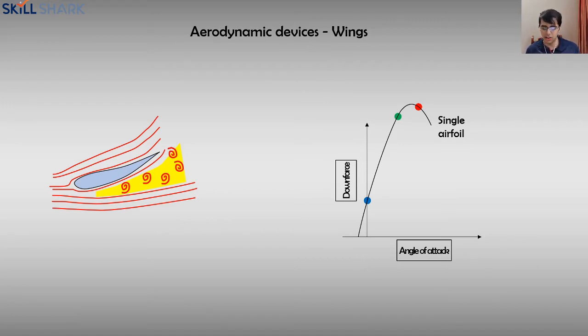And you see a lot of these cases where they talk about aircraft stalling while climbing, and that's because they reach an angle of attack where the airfoil performance stalls. So that's kind of where that term comes from. Now, there is a way to re-energize that flow. If there is some way to send more air into this zone and re-energize it and decrease that pressure, you'll get rid of that issue, just to drive that turbulent flow away. So that's called flow re-energization.